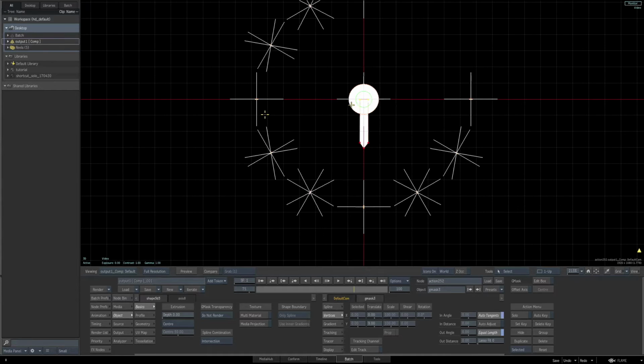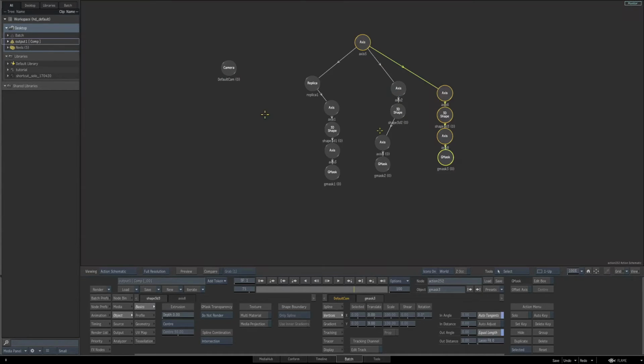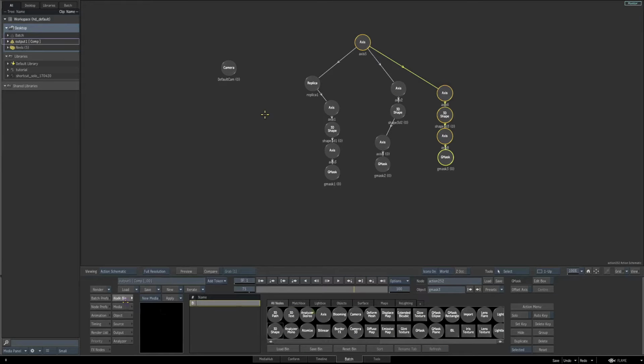Now we want to add a tail or a top part of the dial. So let's go back to our schematic once again. Drag out an additional 3D shape. And since I didn't have the main axis selected, I will manually create the connection by clicking and dragging off at the axis onto the new axis for this 3D shape to create our parent-child relationship.